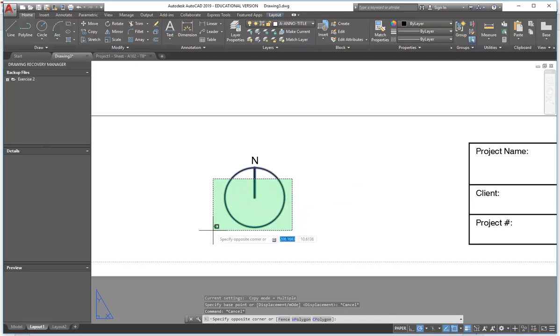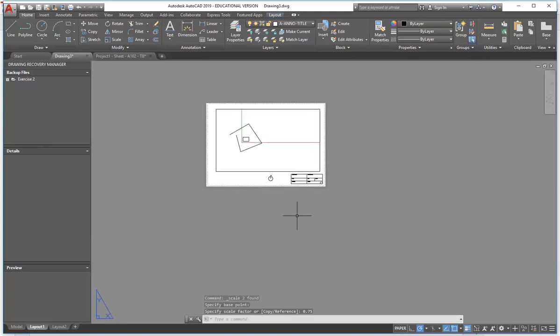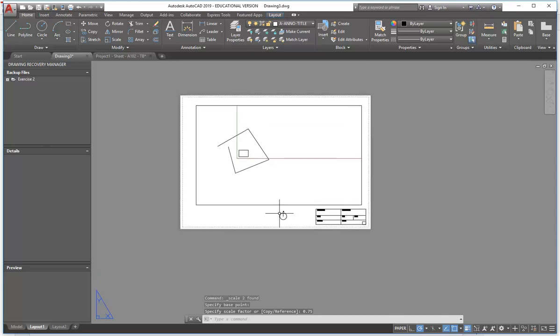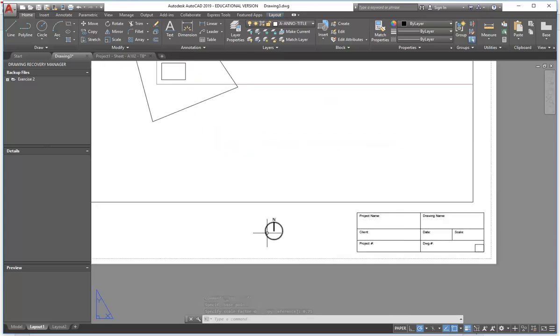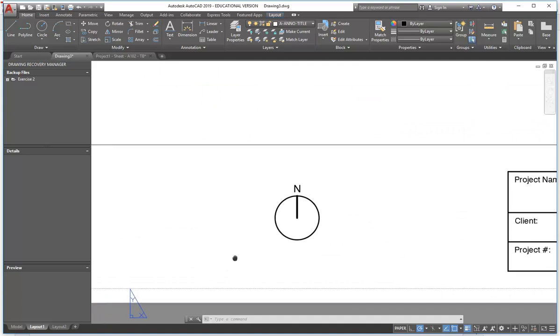So it's a good chance to look at the scale tool as well, because that's a good thing to experiment with when you're changing the size of these objects. I've selected my lines. I'm not going to select the text. And I'll just click scale and click the base point, which I'll make the top of the north point, so it scales to that point. And I'll type in, let's try 0.75 to make it 3/4. Maybe that's what I want. Anyway, do what you want. Whatever you think looks good, as long as it's readable.